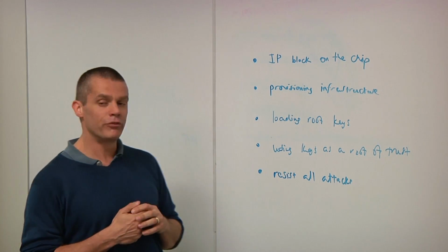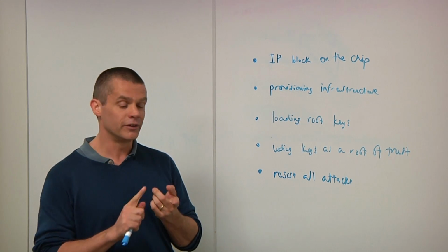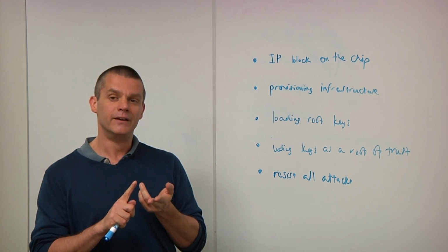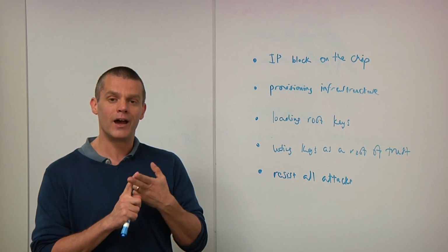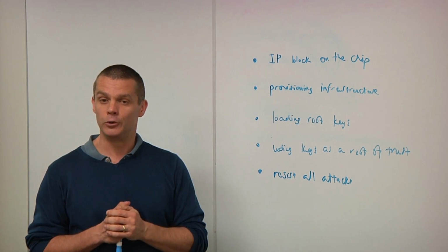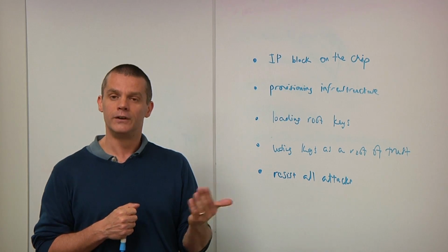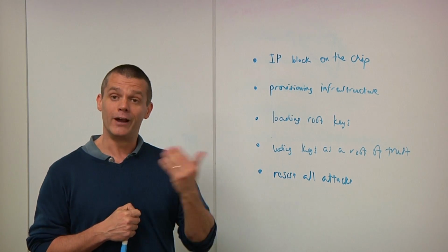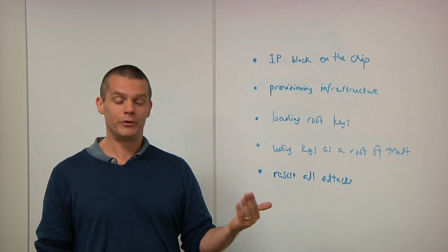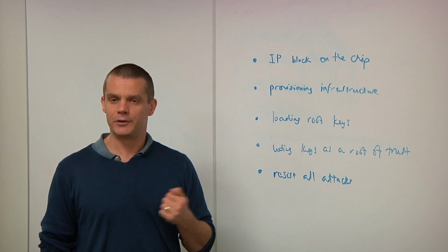So those are the foundational pieces. What do we mean when we talk about an integrated root of trust? It's about a block that can consume keys and use them securely, and an infrastructure that sits behind it, generates those keys, loads them, and retains the information it needs to do things after the fact. These are keys that you load during a chip's manufacture, but you leverage them later. So you can use it to help secure the chip, but then when you put the chip into a device, you can leverage those keys you built in earlier to add whatever keys the device maker wants to.